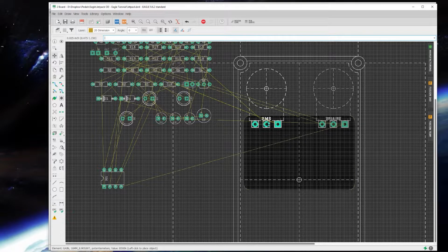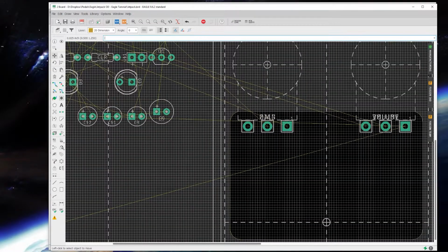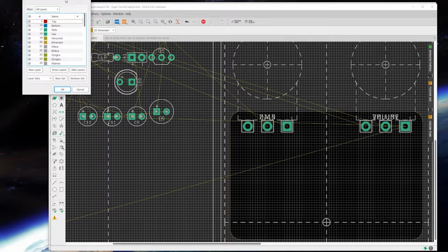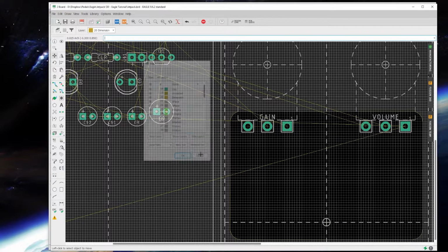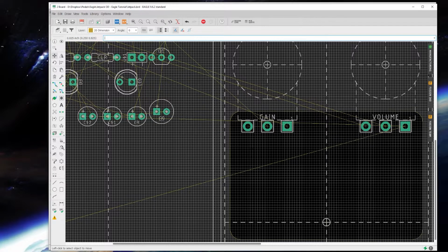If it is confusing, you see here that's got what looks like gobbledygook. That's kind of discernible. It says volume. This is showing on the back layer of the silkscreen that's going to be on the back side of the board. The name is there as well. So if that's bothering you, you can go over to your visible layers and turn off back names, back names, 26. And now it's legible and doesn't give you a headache like it was just giving me.